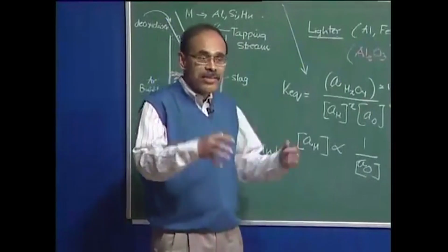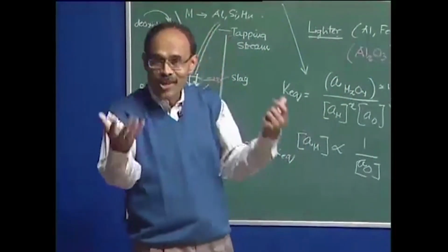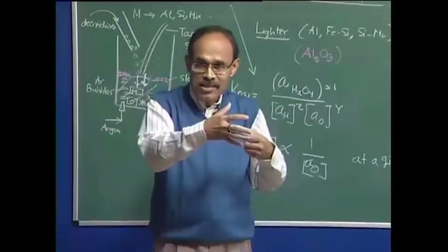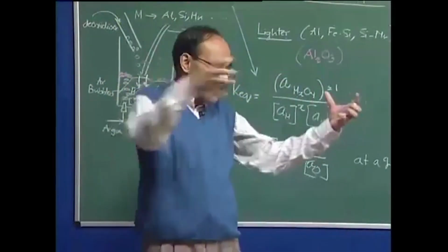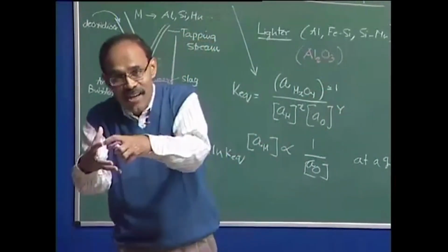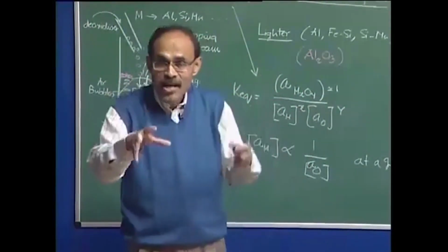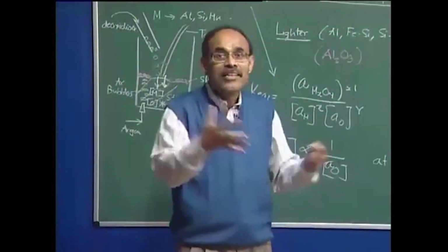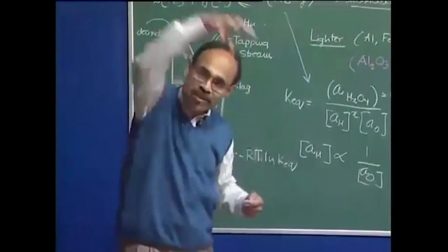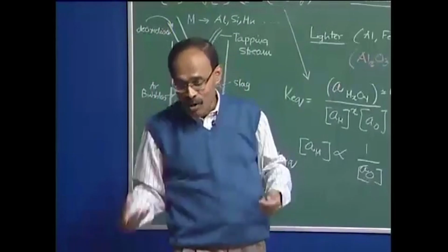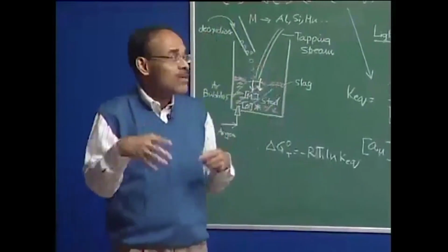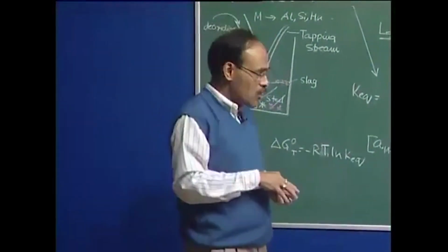Now, once the deoxidizer element gets into the bath, it melts and dissolves. Once it dissolves, it reacts with oxygen. So it's a mass transfer process, because oxygen has to find a dissolved deoxidizer element, and the dissolved deoxidizer element has to find an oxygen atom, and that's how they collide and form a new phase. This is the mass transport step, and therefore we need some kind of stirring. That stirring is initially provided by the convection generated by the falling stream, or alternatively, when the intensity dies, we have gas injection, which is always being used, and that gas injection gives rise to stirring, which aids the deoxidation process itself.